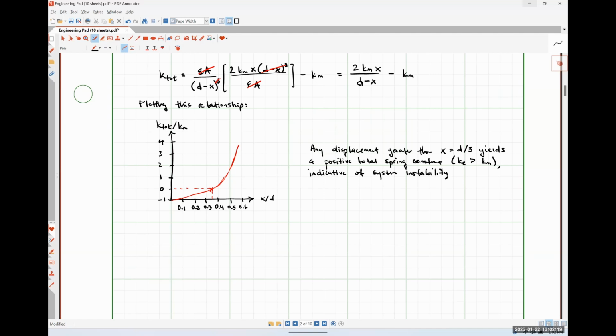What I mean by that instability in the system is effectively we have a positive feedback situation where a very small change in increasing displacement causes a very large rapid change in the force, which feeds back on itself, causing the plates to snap together, right? So that's what I mean specifically by the instability there. It's behaving as if it were a positive feedback system.